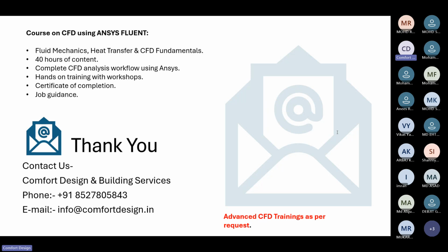And how would you model a cooling fan in a thermal analysis? You can model the cooling fan the same way I have modeled this exhaust fan. Yes, there will be different boundary conditions. There will be convection and conduction, and if you want to perform dedicated cooling analysis for electronics, there is a tool called ANSYS Icepak, which is mostly used for electronics cooling. We can do that kind of analysis in that as well.